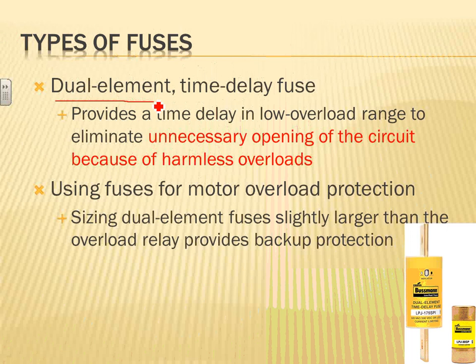Circuit breakers, yeah. The more I teach and train contractors, the more I almost change my mind to fuses. I really do. The people who maintain the system will tell you, if a fuse blows, I know it worked. If a circuit breaker sits inside your building for 2 or 3 years and is not properly maintained, you really have no idea if that circuit breaker will trip and act exactly how it's supposed to be. Now that's where 70B becomes a big deal.